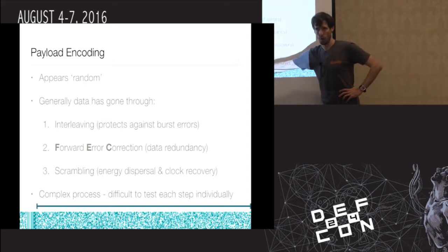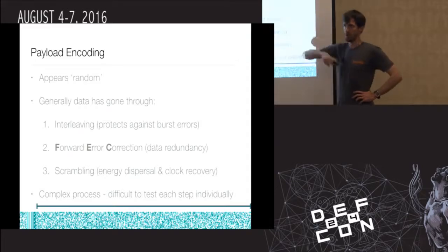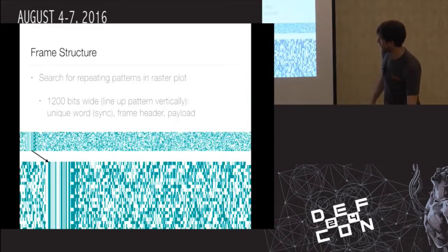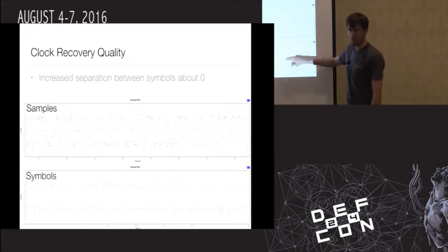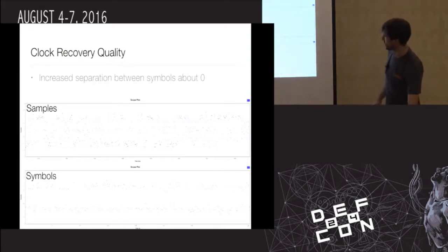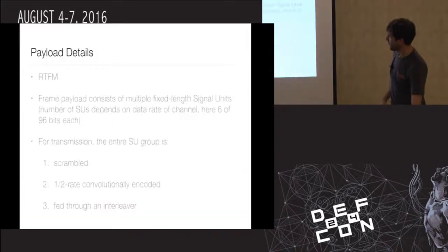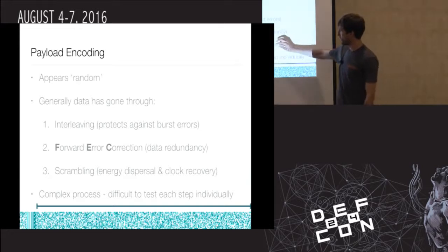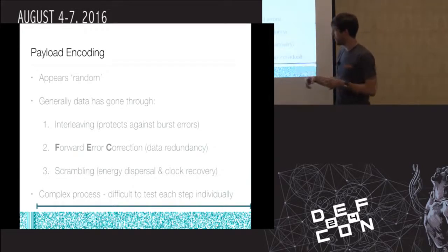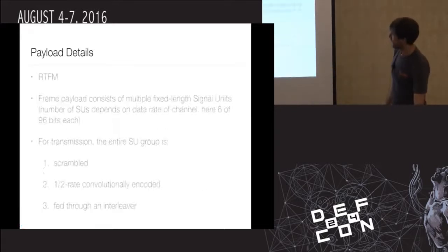So you want to have as many flip bits as possible so that there are these excursions to either end as often as possible. If you don't do it as often as possible, then you may lose synchronization. And there are fixed scrambling codes that use a polynomial in a shift register, and then you can actually deterministically figure out what that is.